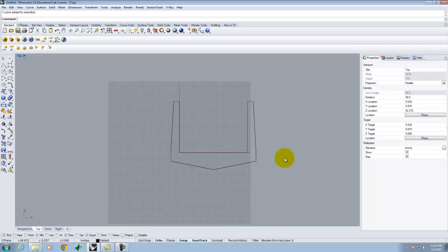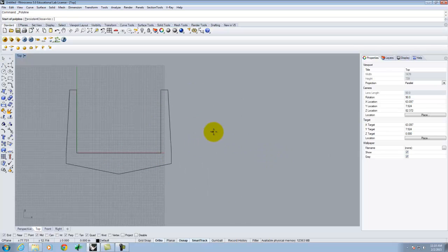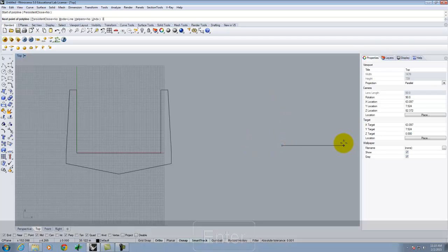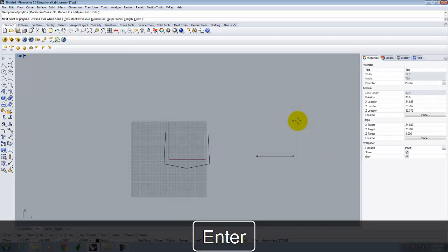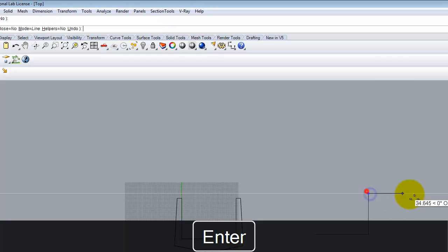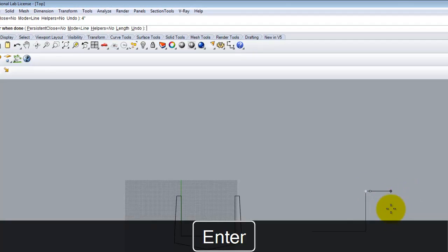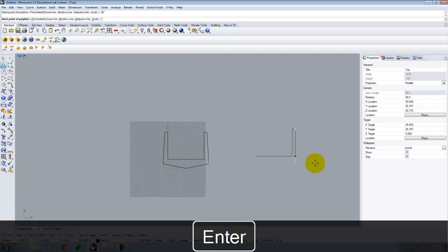Okay? So you can do this by drawing little helper lines instead of doing the relative coordinates. It's just a lot more efficient if you do it. So for example, I could go 36, or it's 48, sorry, 48 over, perfect, we're going to go up 36, and we could go over 4 inches, oops, 4 inches, and then when I got to this point here, I can say, okay, well, let me go down my 36, and then over my 2 inches,